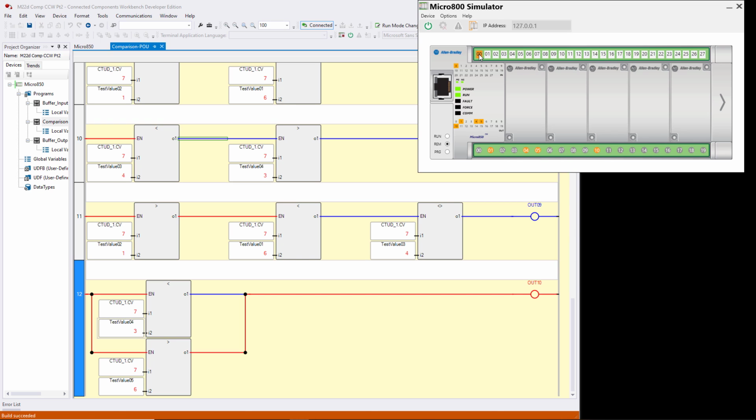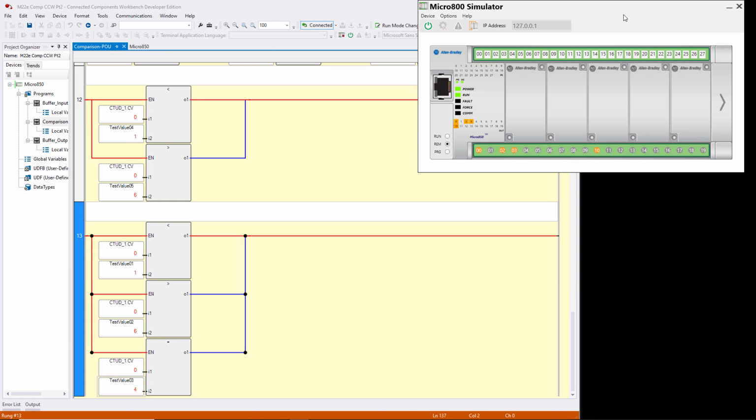If you make them less than or equal to, now only 4 and 5 are excluded. In other words, the limit is set on 3 and 6, and 4 and 5 are false. The rung would be false. So this is a type of limit combination. Now there's actually a limit instruction that we will get to later. Okay, we have one more